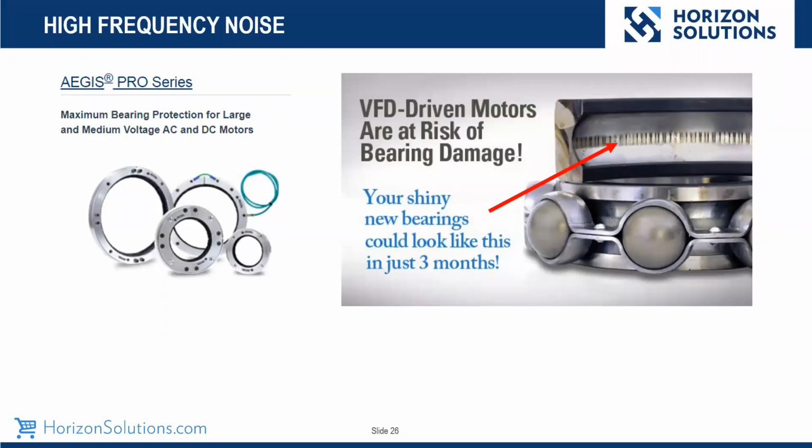What happens is you start to get fluting, and that fluting is on that race where the red arrow is. That fluting becomes a repeated pattern, and then you end up getting chattering in your bearings, and eventually failure. The other thing that happens is it also circulates through the ball bearings or the roller bearings, and it causes a frosting effect.